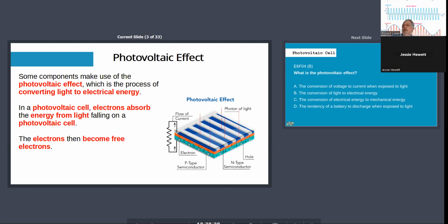that can move, just like if you apply a voltage to cause that to happen, or most any other kind of energy. You can actually do it from applying enough heat, which is the way old vacuum tubes worked. You heated the cathode up enough for it to create an electron cloud of free electrons around it, and then the voltage between the plate and the cathode would cause those electrons to travel across the vacuum of the tube.